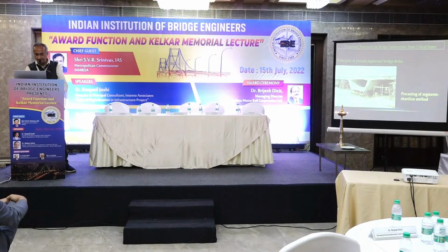You can see an example of such a bed. The trickiest part is adjusting the already precast segment in 3D using a special vehicle which is supporting the precast segment, so it can adjust in 3 dimensions. I think MTHL has got far more sophisticated machines than this.